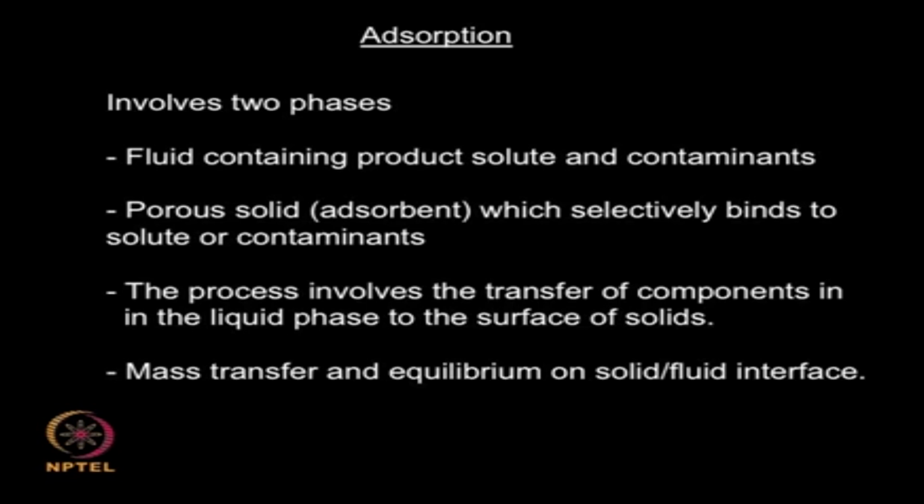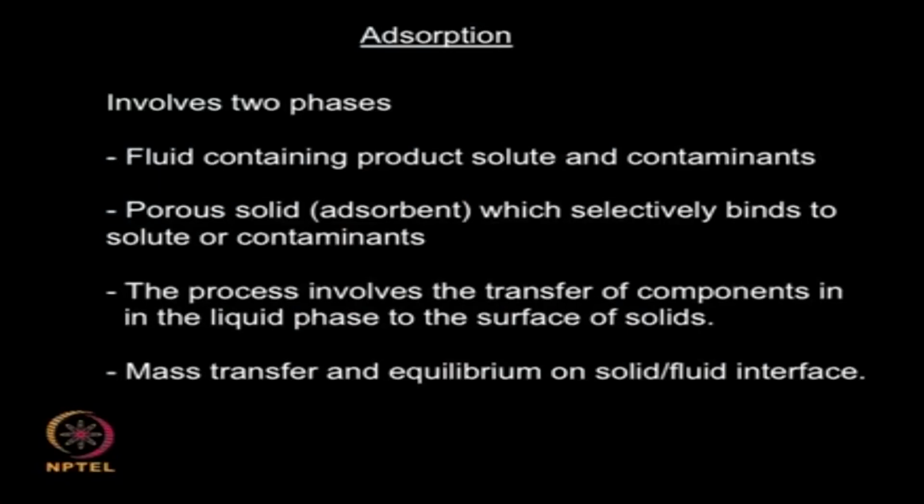So depending upon the mass transfer, if the mass transfer is very fast, I will perform the adsorption very fast. If the mass transfer rate is very slow, the adsorption also will be very slow. So I need to give sufficient time for the solute to get adsorbed, and depending upon the equilibrium concentration I will decide how much of solid I need to add into the slurry. So the mass transfer and the equilibrium determine the thermodynamics and the kinetics of the process. Mass transfer determines the kinetics, equilibrium determines the thermodynamics, understand.